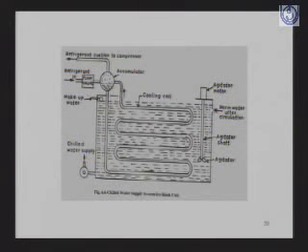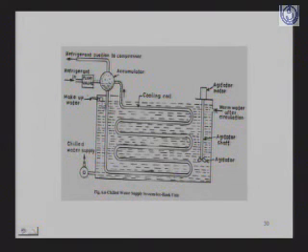This is the diagram to show you the chilled water system. These are the cooling coils. This is the chilled water, and there is a refrigeration cycle. You can see the agitator, and this is the chilled water supply. If you want to make up the water, more water could be added. Warm water after circulation will come here. These are cooling coils. This is the refrigerant going to the compressor, and the refrigerant coming from the float valve. These are the evaporator coils.